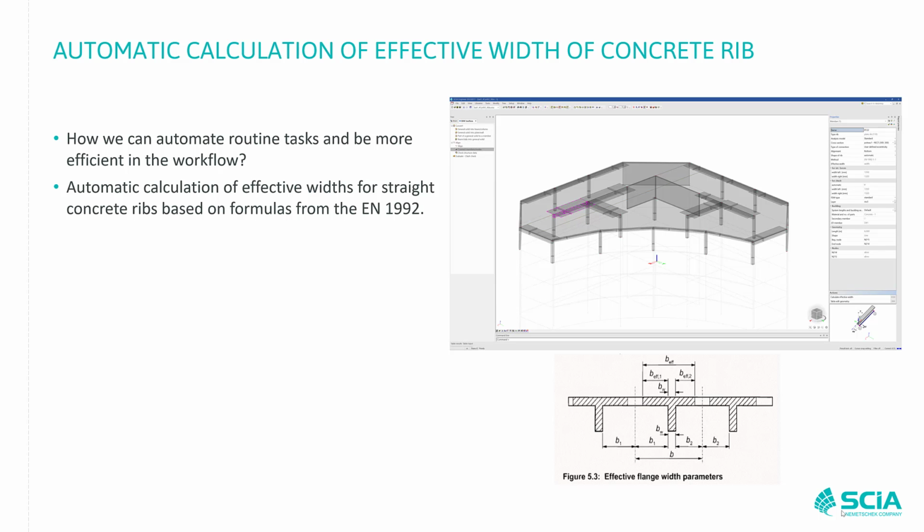The first one related to the calculation of internal forces in the case of the finite element calculation, so which shape of the cross-section will be presented in the calculation. And then also in the case of the checks, you have the possibility to define your own effective width, and it needs a lot of calculation beside our software, on paper or in an Excel table.